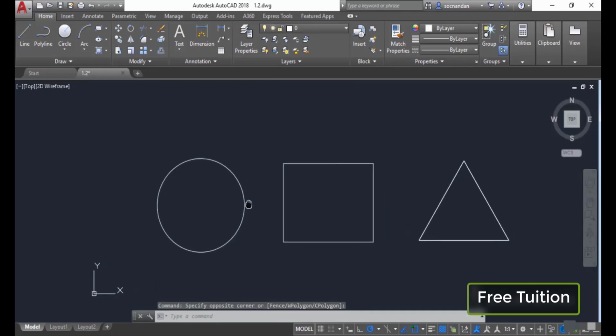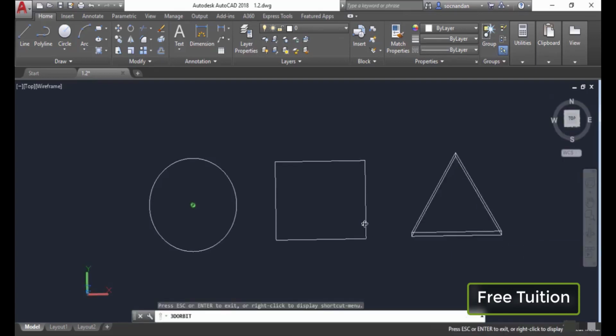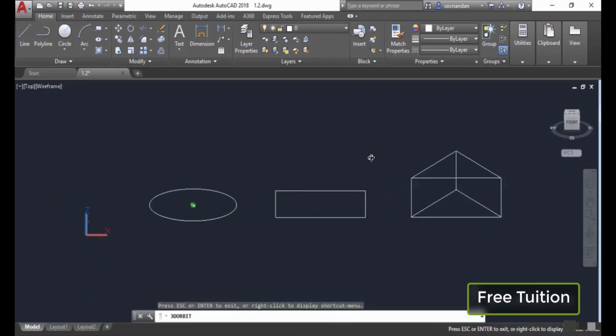We can also access the 3D orbit tool, and using the 3D orbit tool, you can see this drawing from X, Y, and Z axis. Currently we are able to see this drawing from X and Y axis, or from the top view only, that you can see here with the top view. But in order to see it from the 3 axes, or if you want to see the height of this drawing as well, simply go to this orbit tool from the navigation bar, select the orbit tool, and now orbit your drawing just like this.